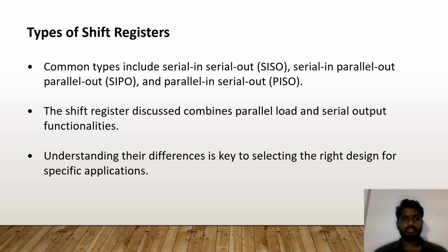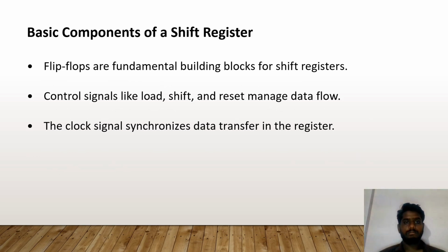Types of shift registers. Common types include serial in, serial out; serial in, parallel out; and parallel in, serial out. The shift register discussed combines parallel load and serial output functionalities. Understanding their differences is key to selecting the right design for specific applications.